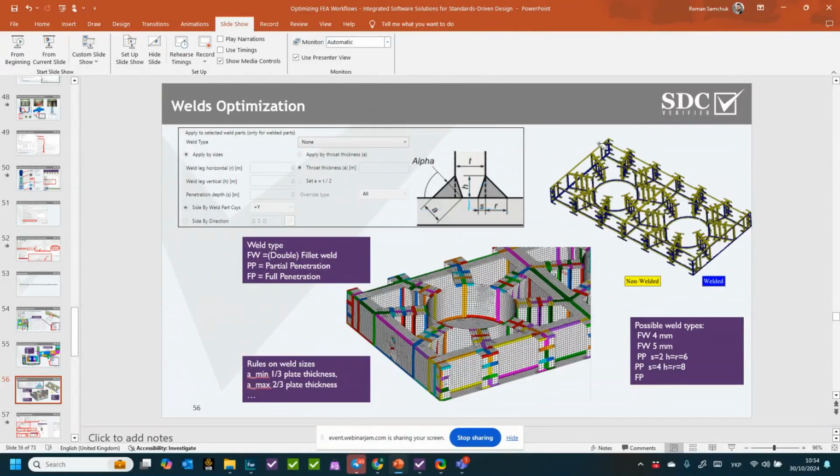And by the way, what's also more important for fatigue, it will also define which plate is welded and which plate is a base plate. As you know, for fatigue, when defining the notch classes, this is essential because the weld related to this plate is having lower characteristic fatigue strength than the base plate, which is sometimes called non-welded part. So yeah, both are available.